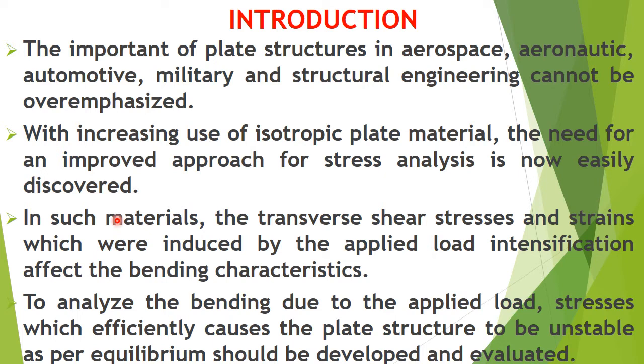In such material, transverse shear stress and strain, which are induced by the applied load, affect the bending characteristics of the plate structure. So we analyze the bending due to the applied load stresses, which can cause the plate structure to be unstable as per equilibrium.